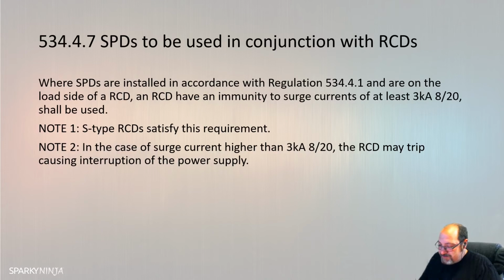And then table 534.4 I think would be the most useful one, which suggests different connecting types depending on the supply system being single phase or 3 phase and where the connection is between lines or between line and earth or neutral and earth. So you can see a 3 phase connection type 2 would be used between neutral and earth. Okay, and it gives you a value there.